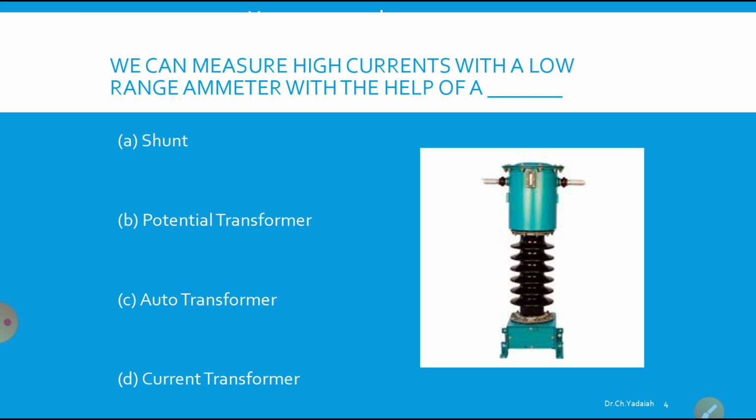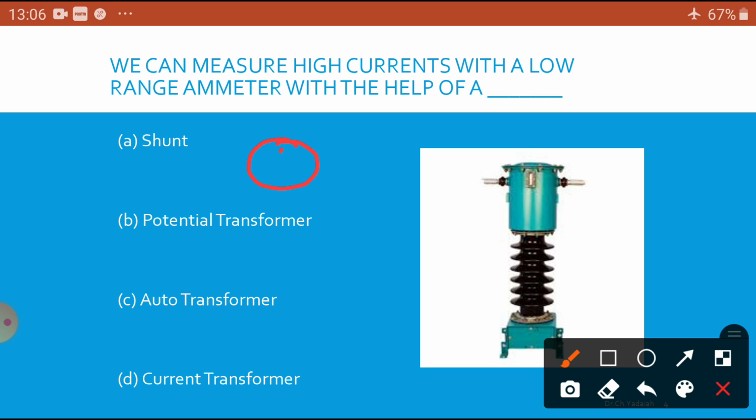Please write. So here, what is being asked? Here he has a small ammeter. You want to measure, for example, 0 to 5 amperes in domestic applications. But can I use this ammeter to measure a current of nearly 100 amperes? If I use the 5 ampere ammeter directly to measure 100 amperes, then automatically it will burn out. But in between I require some media, some broker is required here.